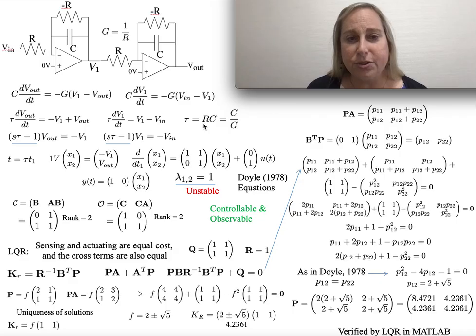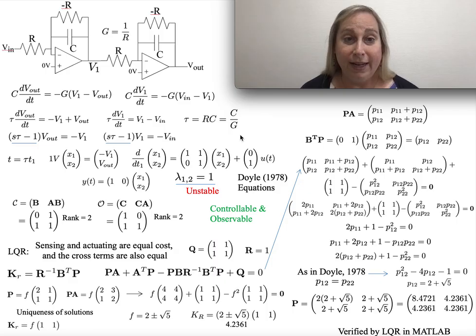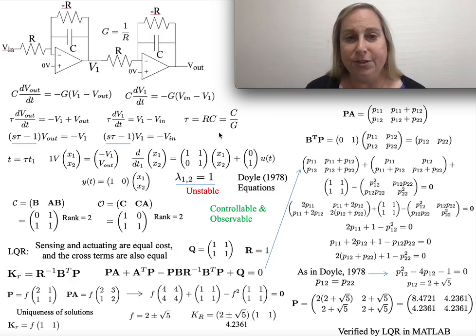Now, one of the things that's super important if you're going to do math along these lines, and I can't emphasize this enough because I've seen this over years and years of different discussions, you really want to realize your tau, your time constant, is capacitance over conductance, which is an RC time constant, right? G is 1 over R. And so this is your time constant. Well, this is why I've got tau in front of both of these cases.